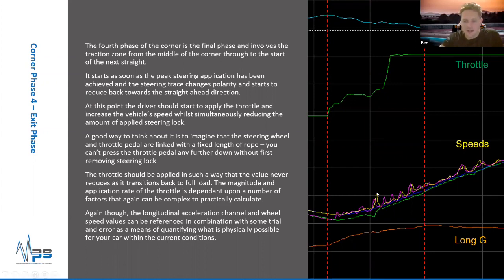Obviously, we've got the luxuries of wheel speeds here. So as you can see, we've got blips of the pink one's a rear wheel speed, and so is the yellow. This is a rear wheel drive car. See, as the driver is applying the throttle, that it starts to break traction. This car has actually got traction control, which is why the engine power will be cut here. You can't see that with the data traces I've got, but this is an example of what it would look like if the car is breaking traction through excessive use of the throttle pedal by the driver.